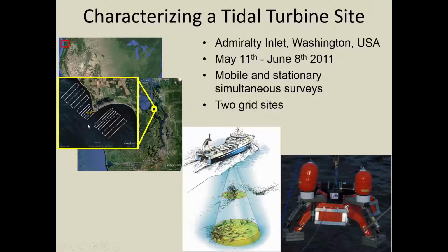We set up in the spring, May or June in 2011, surface surveys where we fished and had surface acoustics and had a bottom package right off Admiralty Head, which was the proposed site for 2 open hydro turbines, which have been put on hold right now, in this package using a BioSonics 120 echo sounder. An important part here is the mobile and stationary surveys were conducted at the same time, so we did have simultaneous data.